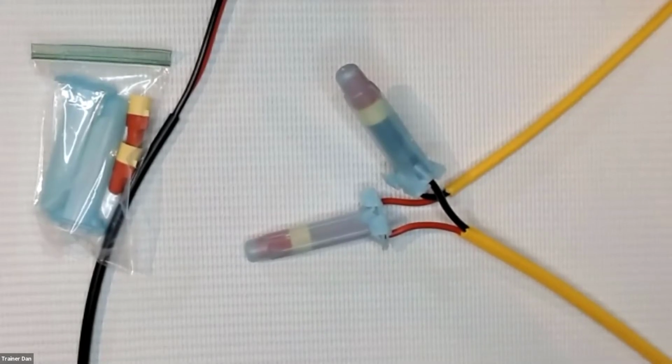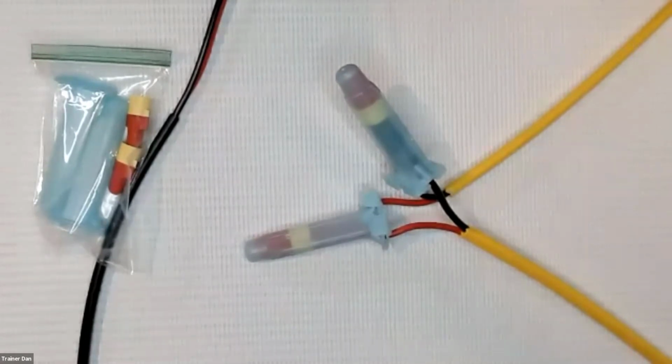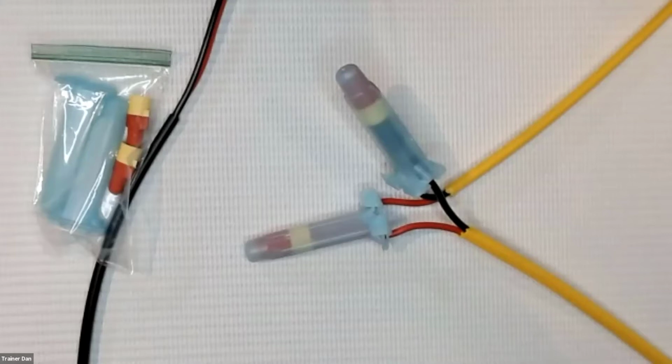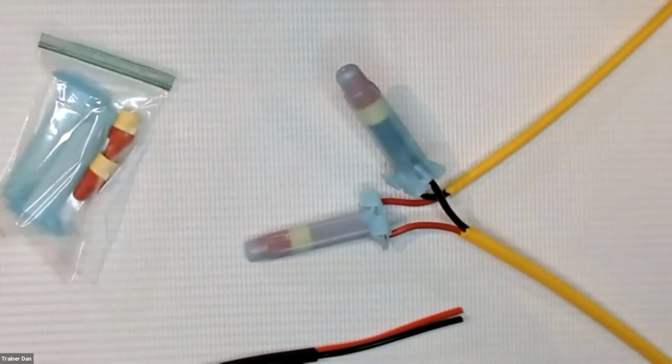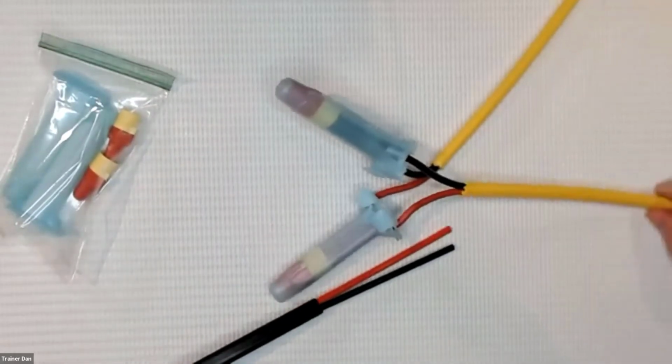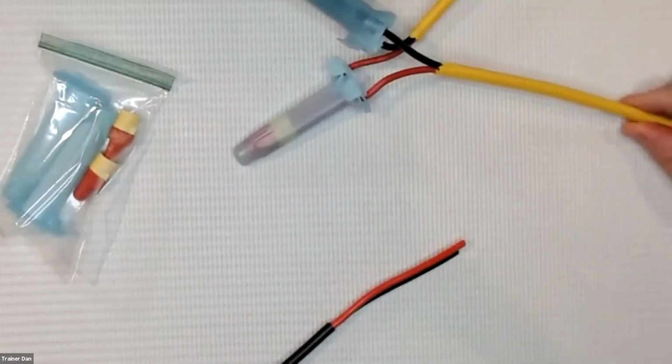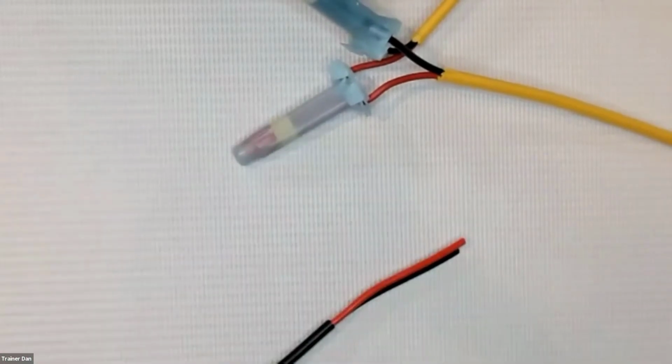Not that I installed it, but I've been on sites where an electrician used stranded cable, even just as a jumper from a controller to the field, and that causes significant communication problems. You've got to make sure it's solid copper cable.